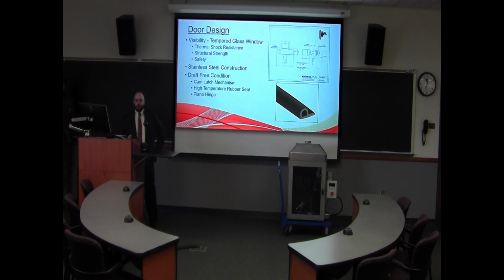And around what glass we chose were a few significant elements. We needed a high thermal shock resistance, owing to the temperature of the flame inside of the cabinet and the differential created. We needed high structural stability, and we wanted something safe. And so that's how we landed on tempered glass. Tempered glass has high thermal shock resistance. It's structurally sound. It's used in automotive glass as well, so that can give you an idea of the order of strength it has. And it's also safe. It breaks into small pieces instead of shards, so if it would fail during the operation of the cabinet, our technician would be safe during that failure.